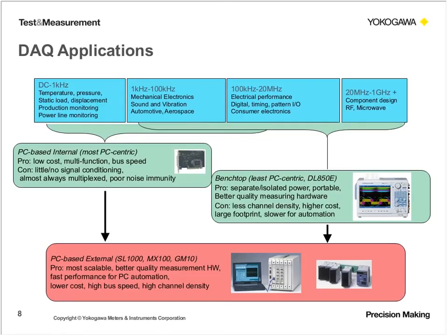Usually you'll find a PC-based or a PC-centric data acquisition solution, and this will be probably in the form factor of a PXI device or LXI, or maybe even, we've been seeing some more commonly used USB-based data acquisition devices. And this is where you'll find a lot of vendors will typically have these low-cost plug-in modules that you will build into a mainframe unit. And each of these modules may have one or several functionalities built into it. And typically you'll find that you have some sort of operating system built into the mainframe of the unit.